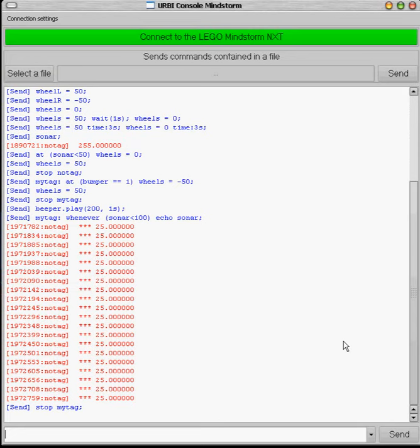Now, we are going to speak about parallelism and do some real cool things. I'm going to use oscillation commands, remember from the motor tutorial, and combine them in parallel with the ampersand command separator. Here I start with the right wheel and I make it oscillate with a period of 3 seconds and an amplitude of 50. And I use an ampersand, which means that the two commands should start at the same time and run in parallel, to oscillate also the left wheel with a different period and amplitude, which is going to make interesting patterns.